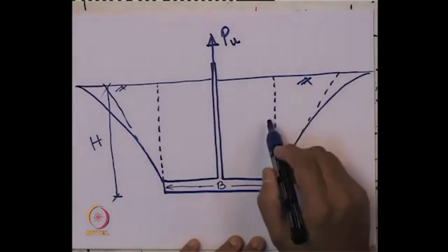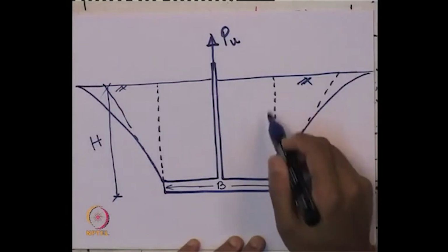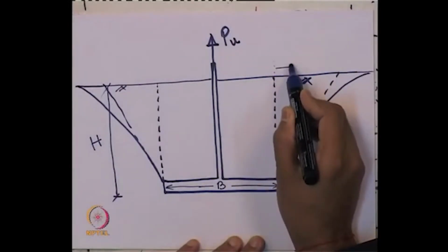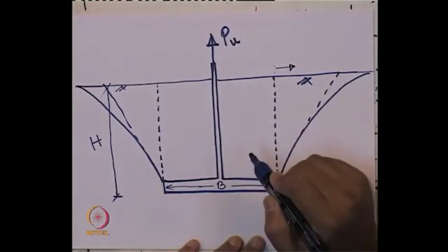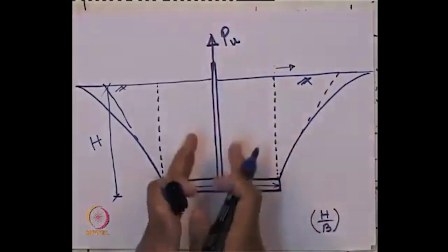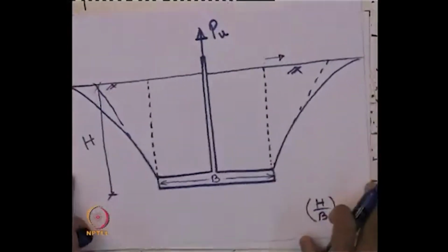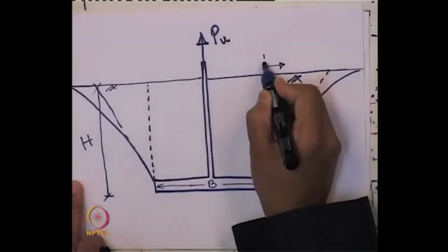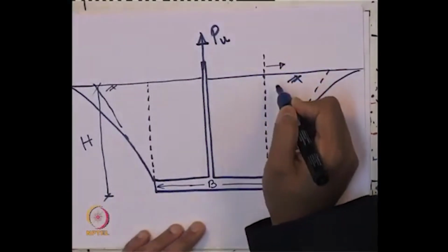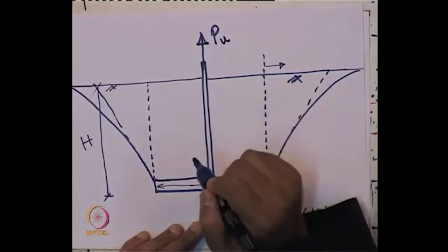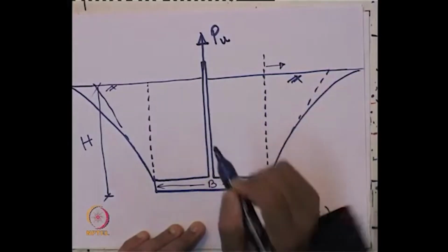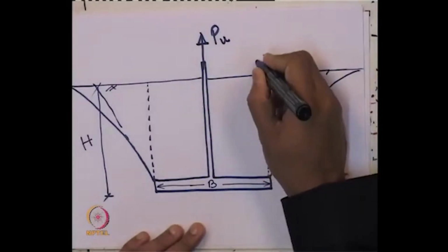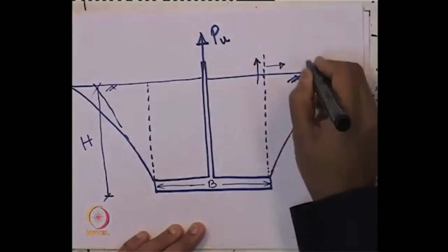Actually, there is nothing, it is within the soil only, we are considering it as an imaginary wall. Now, what will be the lateral movement of this wall if we consider this? This wall is actually moving towards this direction. When we are pulling it out, it pushes this side. Okay? So, that gives us the condition of passive earth pressure. That is why we said that this is nothing but a theory of passive earth pressure. Now, why is it a negative wall friction angle?